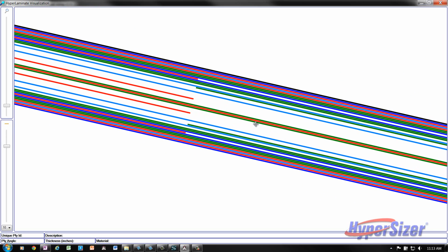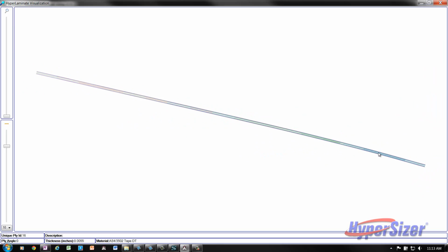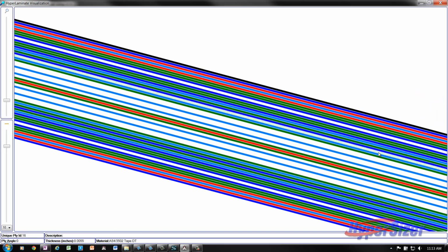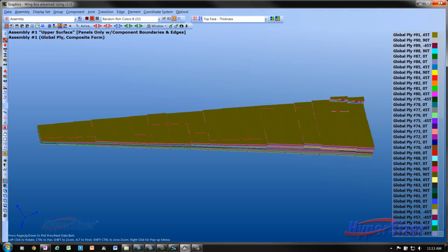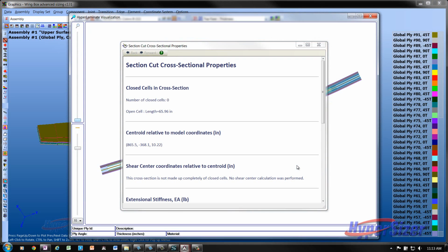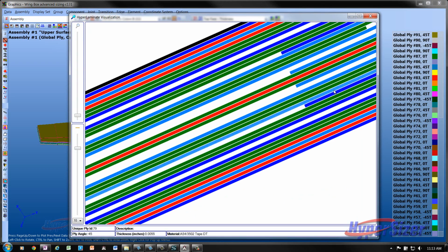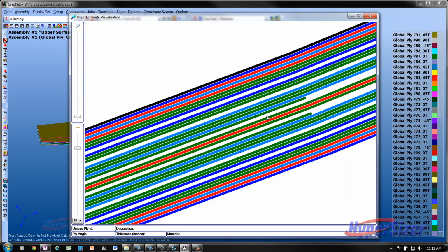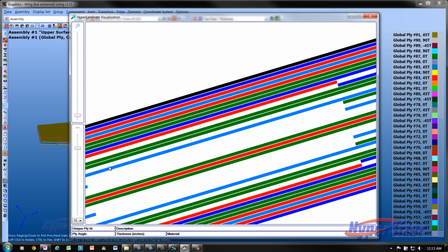And continue on in this manner till you get closer to the root, which you can zoom in this fashion and see the complete laminate definition at that point. I'm going to take this away, do this one more time. So really, with the Shift Control Alt snap line, you can draw it in any kind of arbitrary manner like that and see what's happening. So we can again zoom in right here, zoom in at that location, at this location here, and so forth.